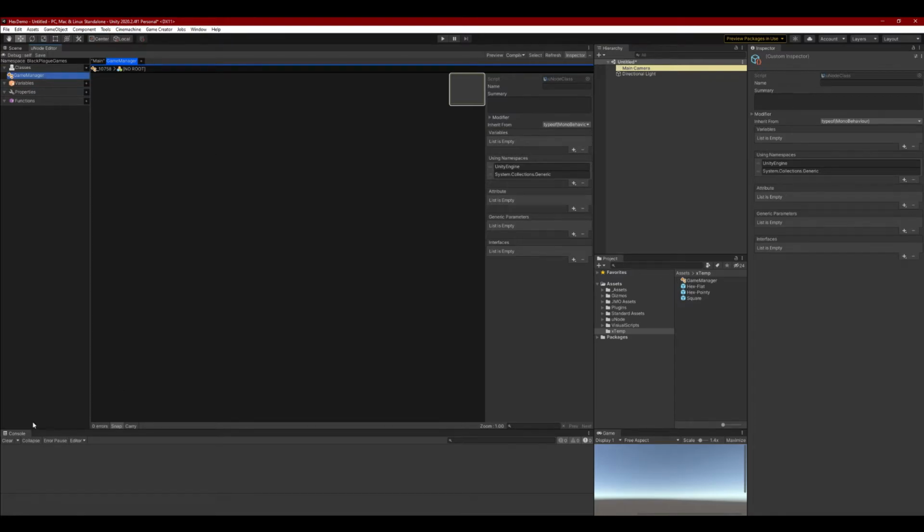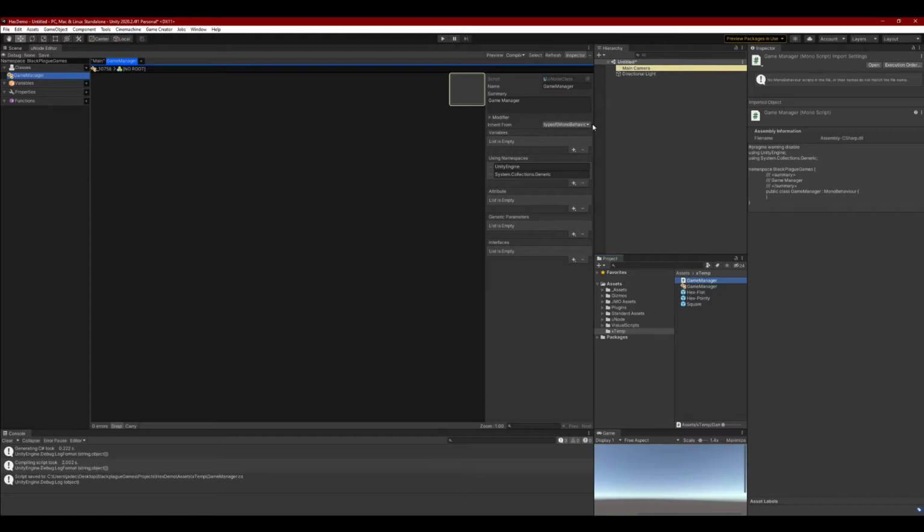Once it's open, you'll notice there are a few areas that we probably need to update, like the summary, what this does, if you so desire. We want to make sure we name it the same as the prefab that was created, so in this particular case, Game Manager. I typically turn off the debug and then immediately compile, so the C# script is generated. You see it takes a bit to compile, and there are a number of load buttons, so I will try and cut those out in the future.